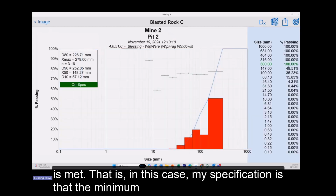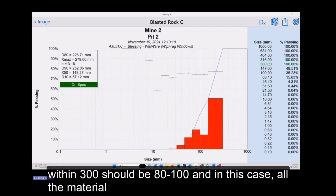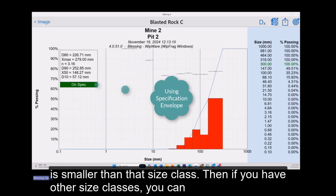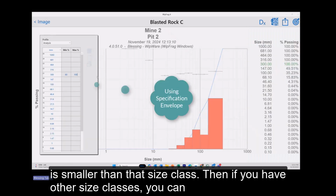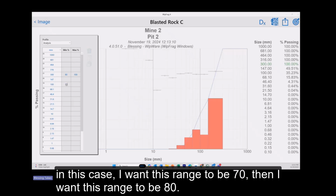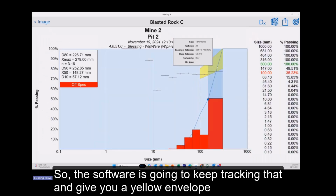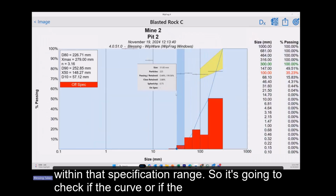In this case, my specification is that the minimum percentage passing within 300 should be 80 to 100, and in this case all the material is smaller than that size class. If you have other size classes, you can include them and set the specification for them. Maybe in this case I want this range to be 70, then I want this range to be 80. So the software is going to keep tracking that and give you a yellow envelope within that specification range.